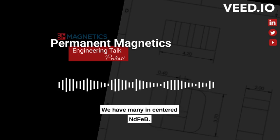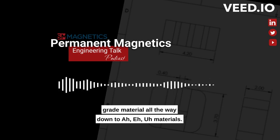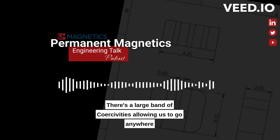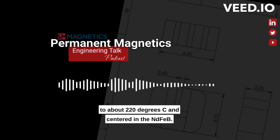In sintered NdFeB, we can go all the way from straight grades, H grade material, all the way up to AH, EH, UH materials. There's a large band of coercivities allowing us to go anywhere from a maximum of 60 degrees C all the way up to about 220 degrees C in sintered NdFeB.